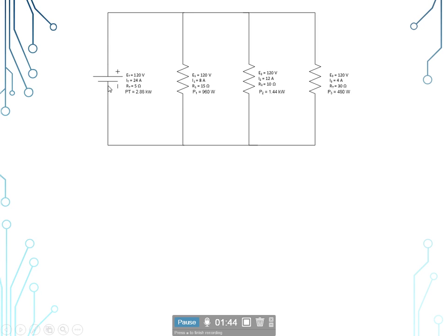So the way that we tell that it's a parallel circuit is we trace this circuit. We have one path up to this point right here. That point right there is called a node. That's where 2 or more wires are joined together. So we have a path here or we have a path here. We come to another node, so we have 2 more paths, one up there, one up here. And then we go through our last load and come back. They all join together at another node, full circle back to the power source. So in a series circuit, we call them series strings. In parallel circuits, we call them parallel branches, and this is a 3-branch parallel circuit.